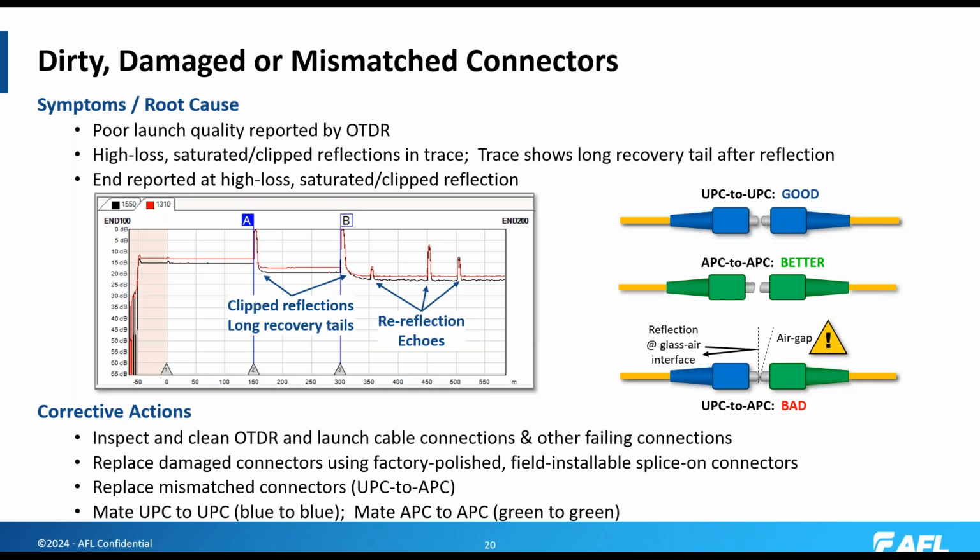Make sure you have no mismatched connectors. If you have blue to green, you're going to have to replace one of those, either make them both blue or both green. And as shown in the illustration here, UPC to UPC will give you a good connection, assuming they're both clean and undamaged.